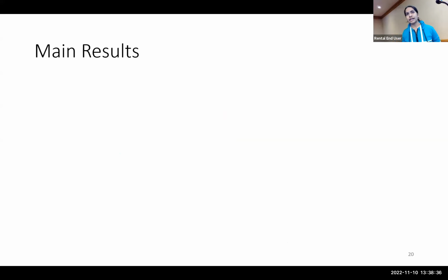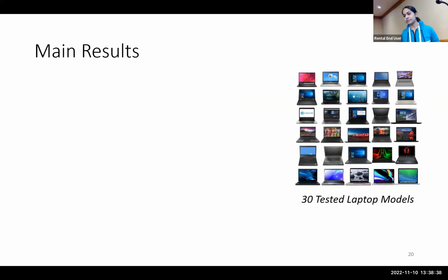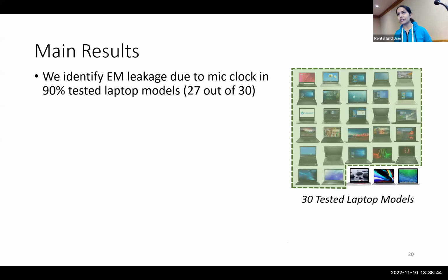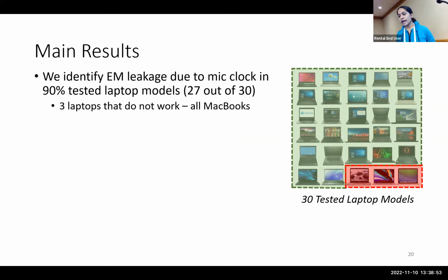So now we'd like to consolidate the results that we've done. So we've tested on a total of 30 different laptop models. And the main result of TickTock is that it works on 27 out of the 30 laptops, which is 90% of all the laptops we've tested. And as you can see, it doesn't work on 3 laptops, and we've identified all of them to be MacBooks. One potential reason could be that there could be attenuation in the EM leakage signal due to its casing.